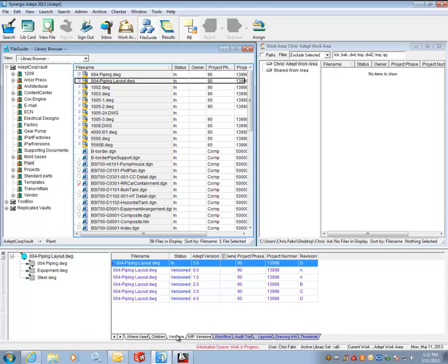Only if you select the Versions tab in the relationship browser do you see the history of the document. Adept tracks a version for each document signed in, as well as revision that can be updated by you at the proper time or, if you choose, automatically bumped up by Adept, say at the end of an approval process.